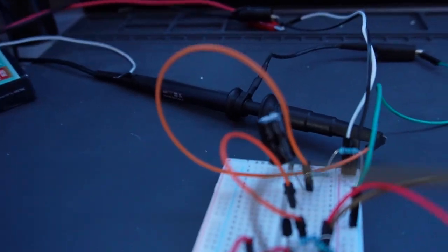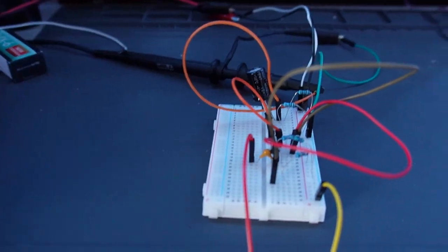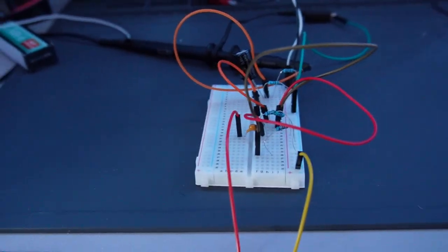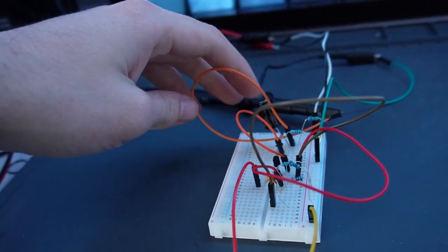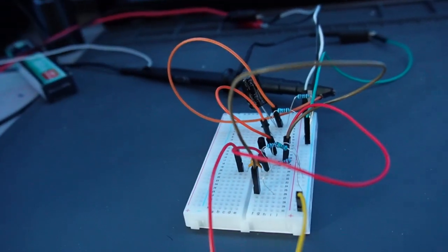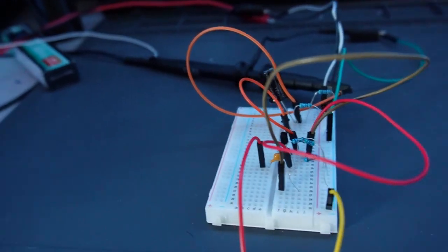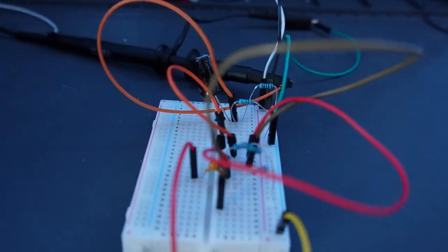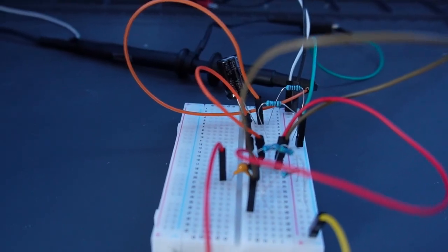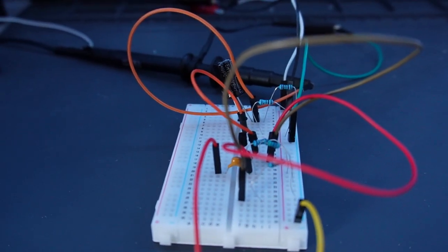I will turn this off because the resistor is getting quite hot. But without doing further calculations, that seems around right. The capacitor here is quite large, so at this frequency of 1 kilohertz, it should act basically as a short, meaning it splits the current equally among the collector resistor and the load resistor. So that seems to make sense.